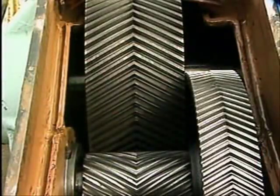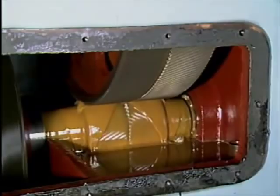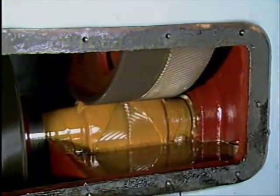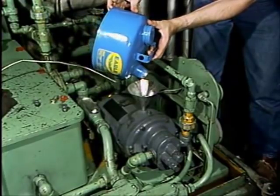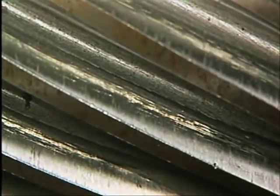Problems with lubrication or lubrication systems can soon lead to problems in a gear set. The basic causes of lubrication problems for gears include using the wrong lubricant, improper temperature, contamination, and insufficient lubricant. One type of gear lubrication problem can occur when the wrong kind of oil or grease is added to a gearbox during routine maintenance. The improper oil for a particular gearbox may not have the proper viscosity or oil additives to handle the loads, speed conditions, or temperatures that the gear set operates under. The use of the wrong type of oil or grease for a gear set results in increased friction and rapid wear of the gears.